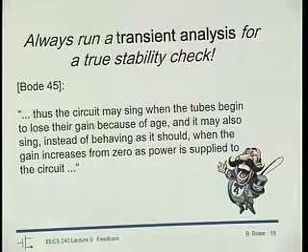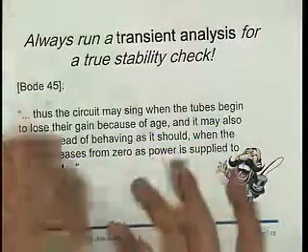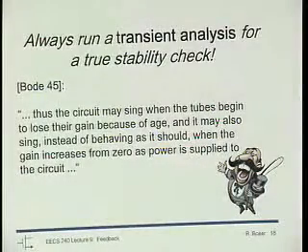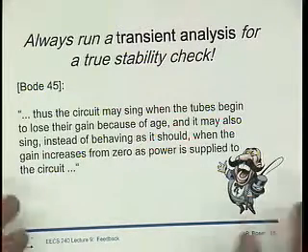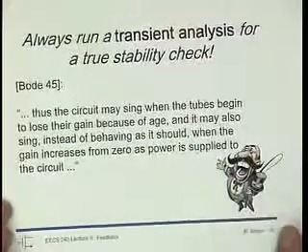You're slowly ramping the supply up, just like it's going to happen when the chip comes back and you flip on the supply switch. If you don't do that, chances are you flip on that supply switch and the circuit never can get to the point where it's operating right. Or more likely, it will sometimes get there, but not others. And you have an unreliable circuit.